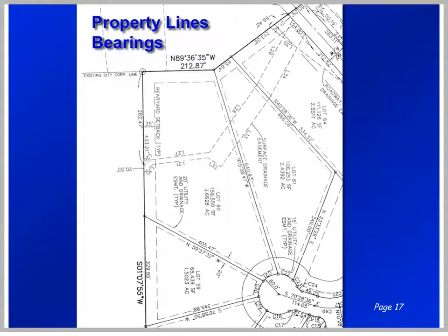This type of site plan is called a plot plan. This is how subdivisions are laid out, showing property boundaries, as you can see right here, which have vectors on them. For instance, you see north 15 degrees 38 minutes and 47 seconds west.